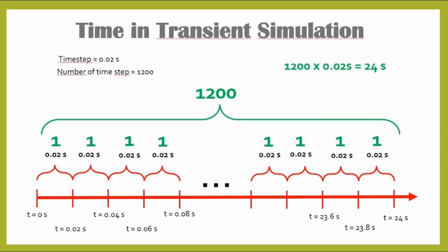In the second part, we solve the same model using a transient approach where the mesh actually moves over time. This is done using the sliding mesh technique, which is more accurate as it captures the unsteady interaction between rotating and stationary parts of the domain. Although it is computationally more expensive, it gives us a detailed look into time-dependent effects such as vortex shedding, periodic forces, and dynamic blade interactions. Use case: ideal for detailed flow analysis, noise prediction, or performance fluctuations.